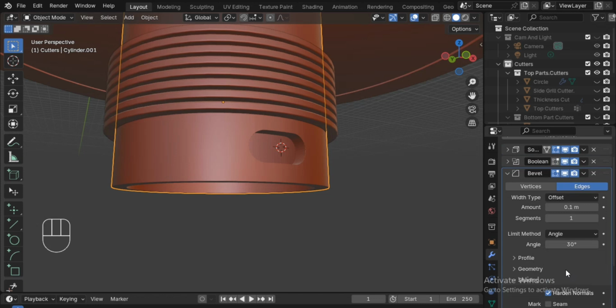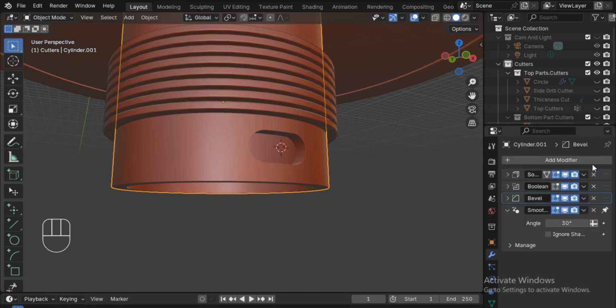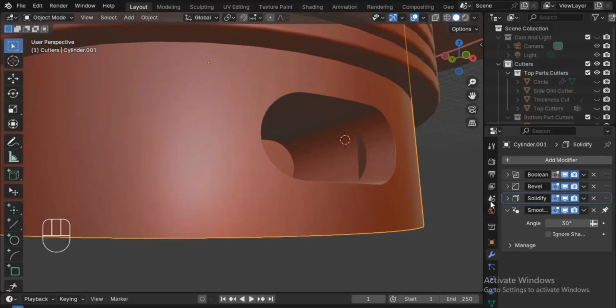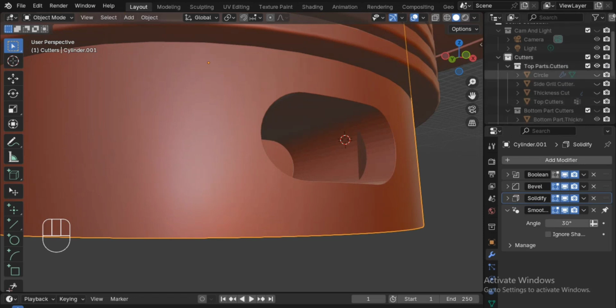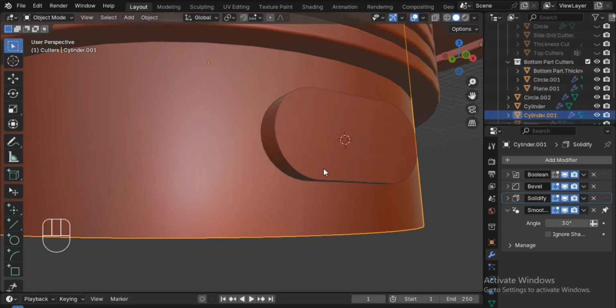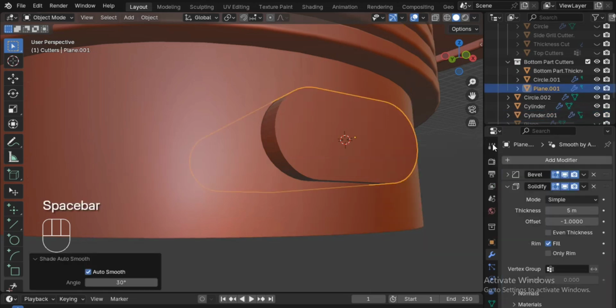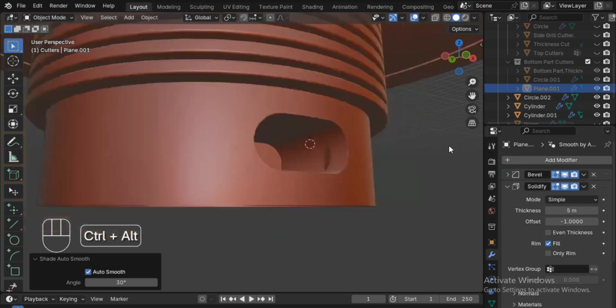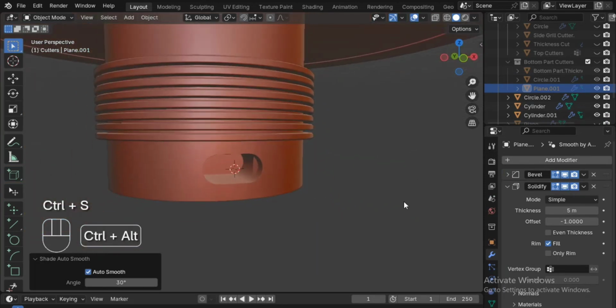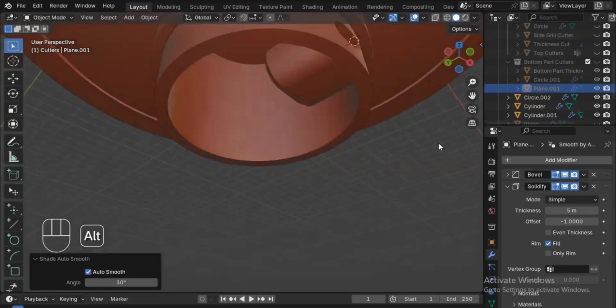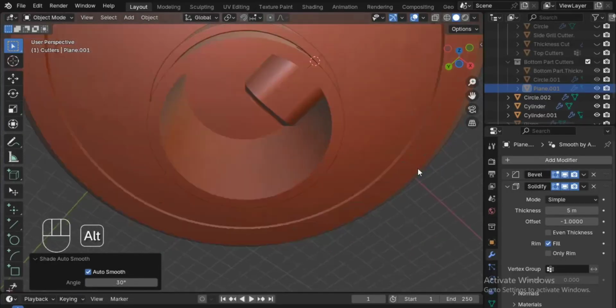And move it to the cutters. And go to generate a new bevel on the mesh, going to the modifier stack, and always check the hard and normal options, so there would be fewer problems calculating the geometry. Normals are calculated properly and no geometry distortion happens. Usually after beveling, more geometry distortion sometimes happens, not just from not checking this option.